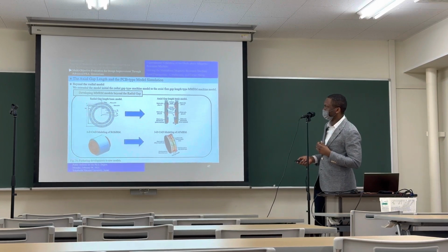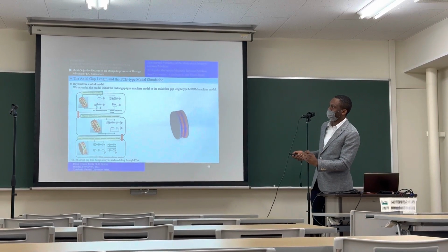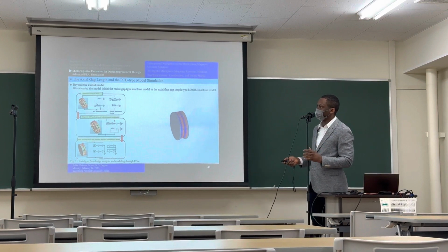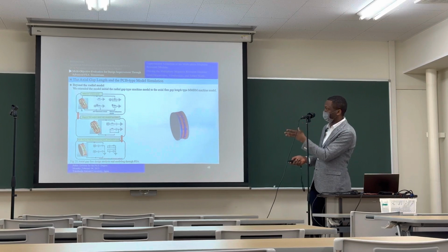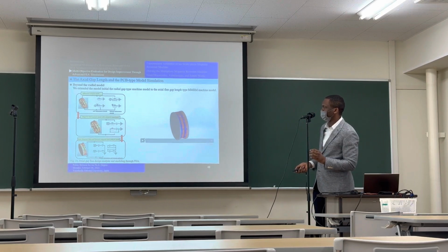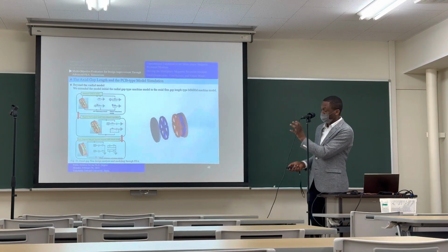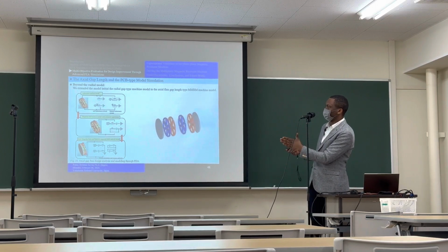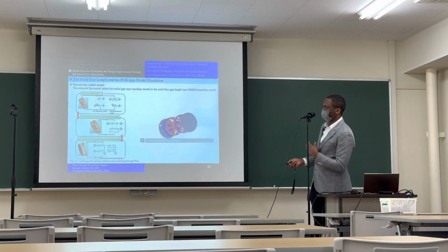For the radial shape, we came out with the 3D CAD model of this machine, and we went further to do a detailed analysis through finite element analysis because it's already validated mathematically. So through finite analysis, we went through the same procedure again to understand the characteristics of this kind of machine. The main architecture of the machine is something like that. For the axial, we call this one the axial gap type, it is going to have 4 coils. The 4 coils are going to be placed axially, 2 on the stator and 2 on the rotor. So you have the stator side and the rotor side.